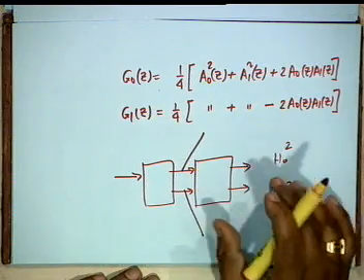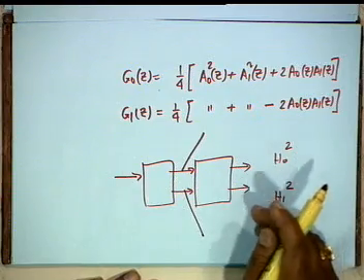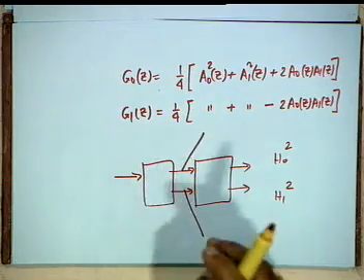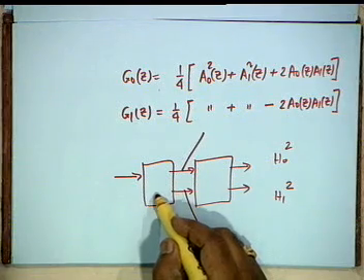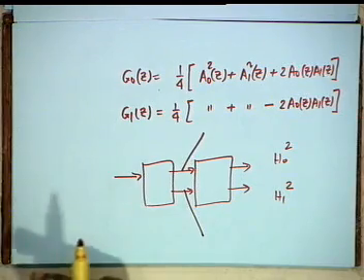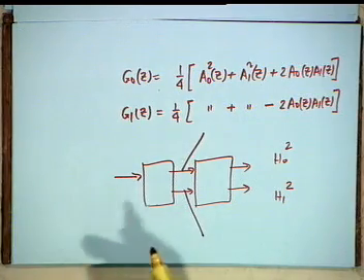So, it is a versatile chip, okay, having a number of output pins. One will be marked low pass, one will be marked high pass. You can also get an output from the first order all pass filter. So, you also get a first order all pass, first order high pass, first order band pass, and in addition a set of doubly complementary filters and a set of magnitude complementary filters. Okay.